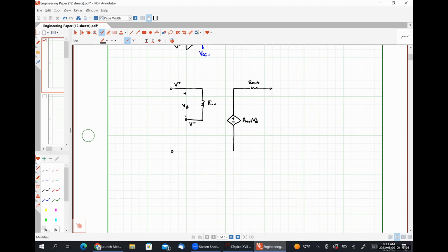And here is that ground rail that's effectively common to everything. And let me explicitly ground things here. All right, so that's my op-amp. Now I'm going to make my external connections. So my output signal is just measured at the output terminal, so it's an open circuit voltage here. My reference voltage is applied between my inverting input terminal and ground. So this is Vref.